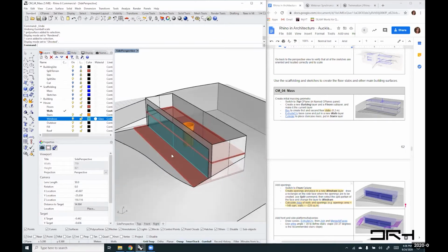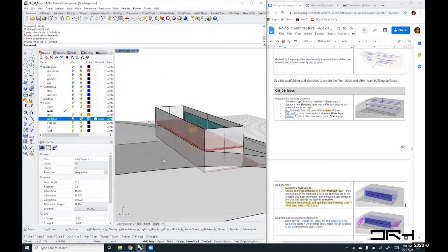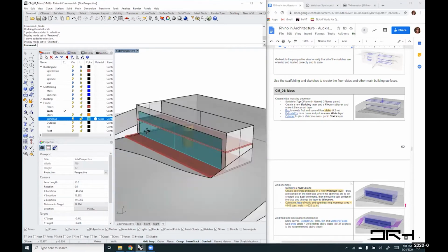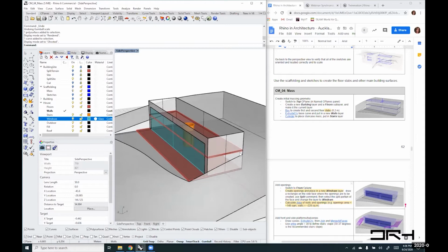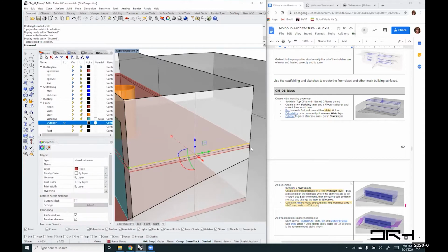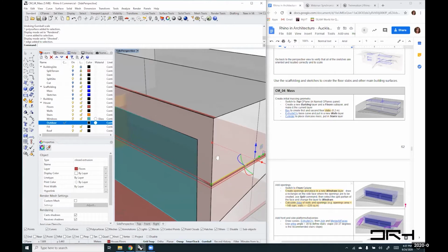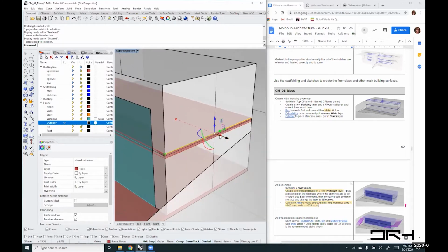And this way we just see what kind of volume we need for the fill as well. And so the way to do that is I will just pick on some of these curves. For example, this one, I'll just be in the outdoor layer first. So with Shift and Control down, this is to select a sub object. Because this is part of the flooring, but I just wanted that part of it. And I just want to extrude.